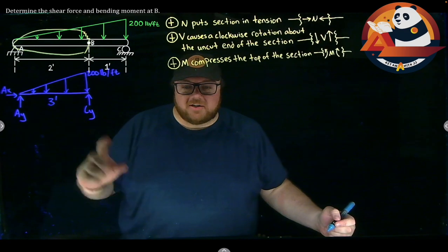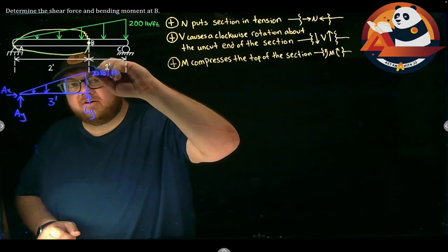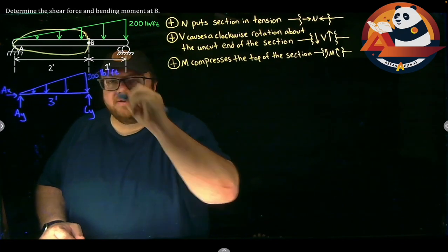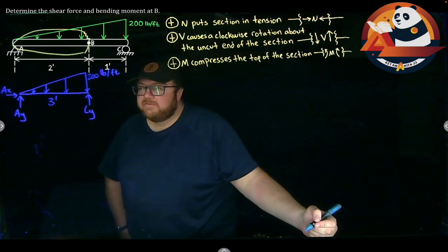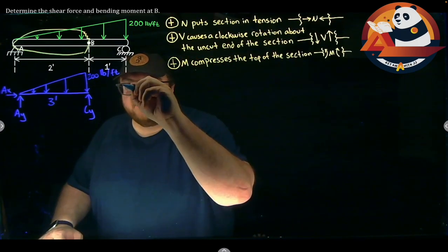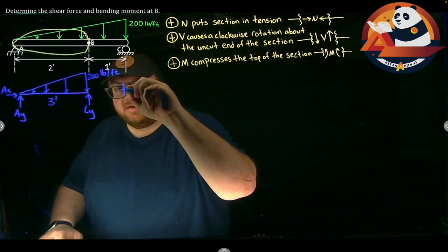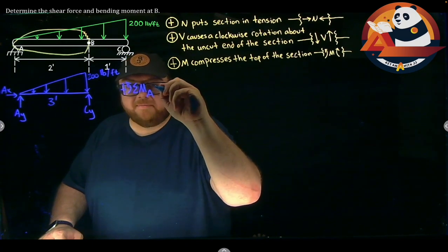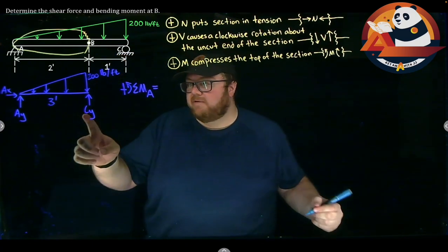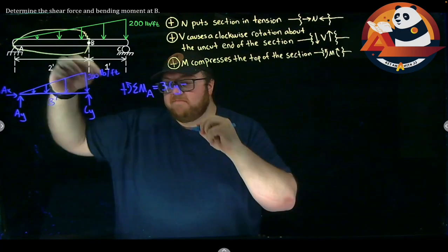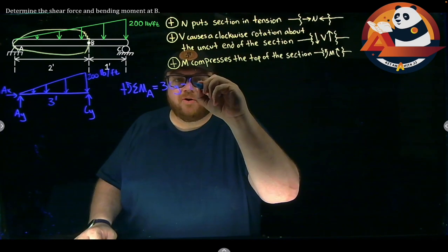So we can come in here and start trying to work with that. Let's move that 2 over just so it doesn't hit the dash. 200 pounds per foot. If I'm trying to find my support reactions, let's just start by summing moments at A. With positive going counterclockwise, that would get me 3CY minus my moment from the distributed load, force times distance.